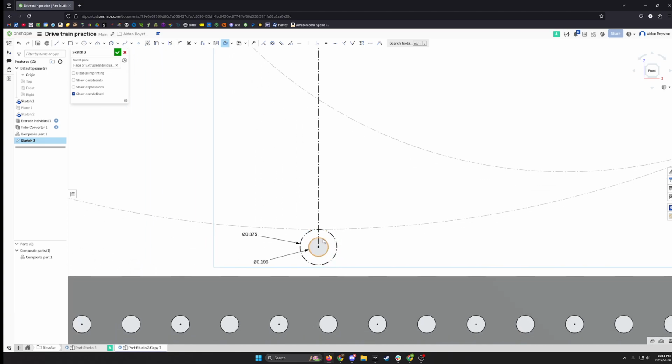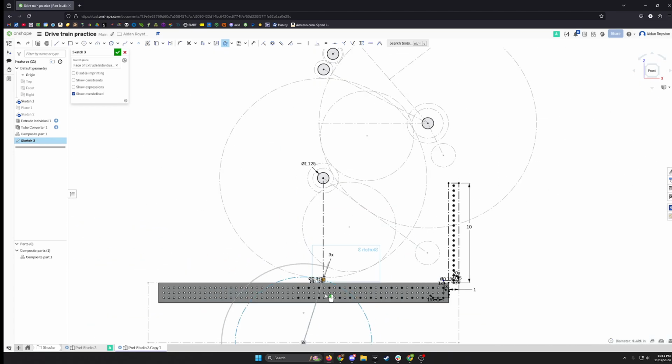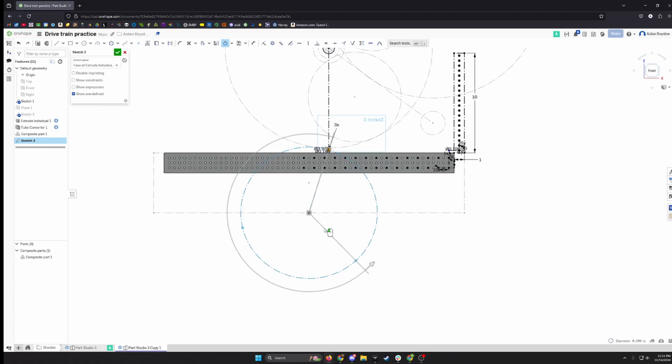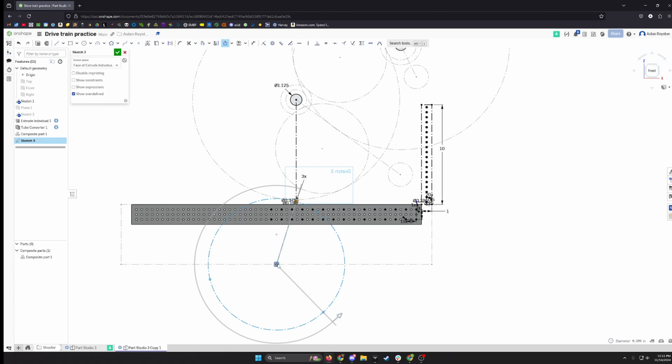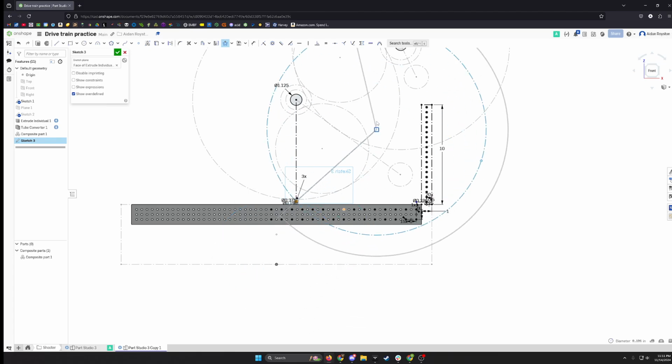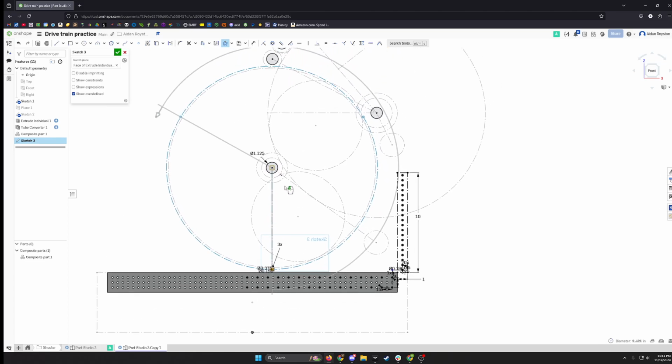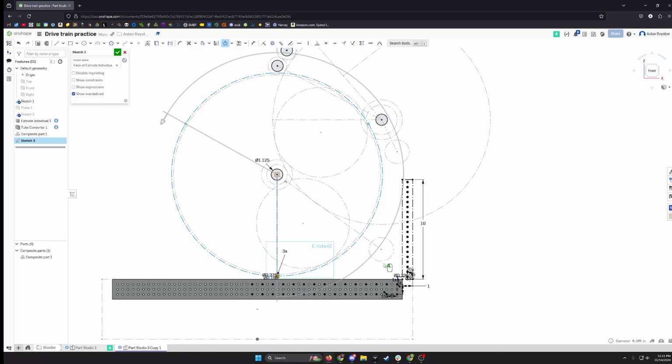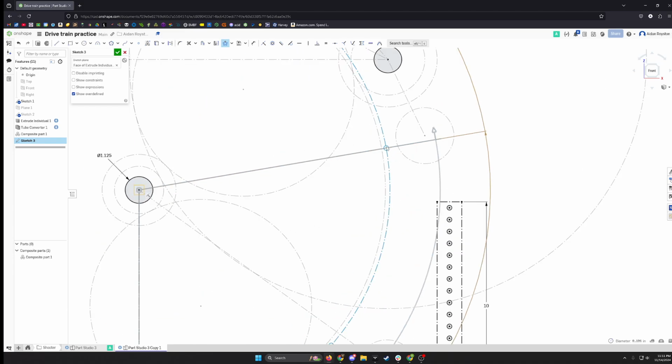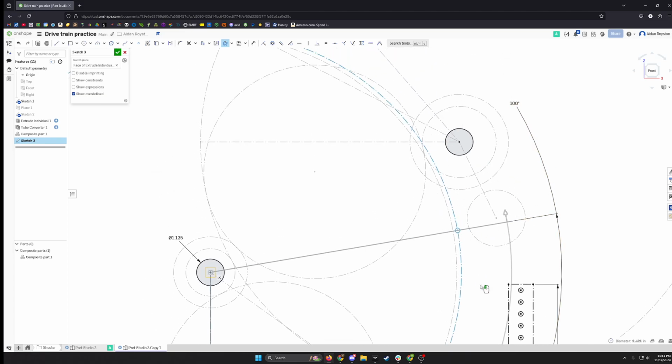So we would just want to select this one right here with just the mounting hole, not necessarily this outside hole. So we select that, and you see it makes it down here across the part origin, which we don't really want. So we can just grab this box and drag it up to right there, just where we want it. And you can see it's still going all the way around at 360 degrees. We don't want that. We can grab this little arrow, bring it out here, and let's say about 100 degrees. That'll work nicely, because you see it'll stop right here, which is about where we want it to stop, so it doesn't interfere with anything that's going on up here.